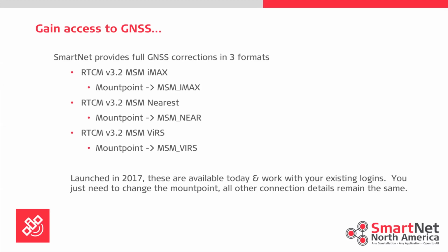They are available today. They work with your existing logins. So you just need to change the mount point to be able to use these corrections. All the other connection details remain the same. They are on the production mount points, so they are on the production ports, so they are on port 10,000. So really all you have to do is update your mount point and you'll be good to go.